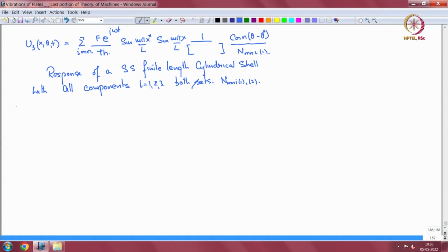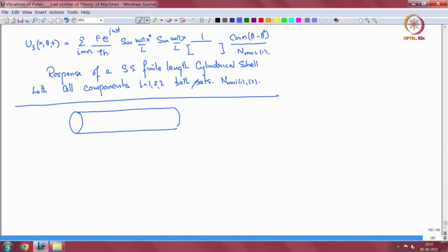Now this is quite cumbersome every time, quite lengthy. In many shells, okay, let us say the aspect ratio is very long, that means the length is much longer than the diameter, then it turns out that in transverse or U3 direction the shell is very flexible, and still stiff in axial direction and torsion, okay.